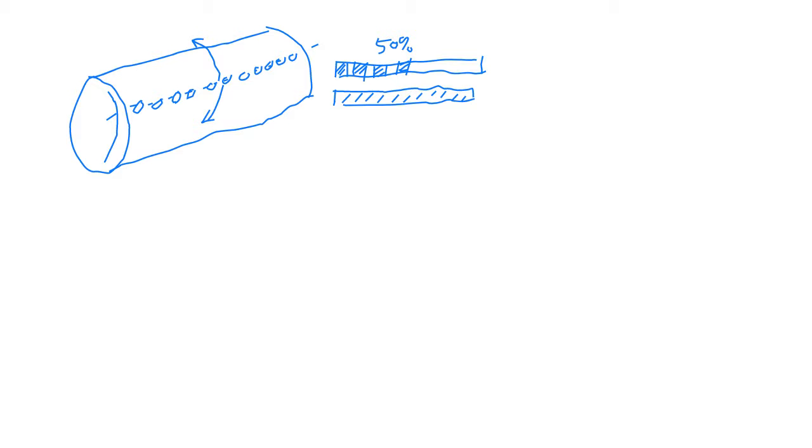Well, ASME always tells us to use the weakest part. So let's say that this is the longitudinal joint. The longitudinal joint is 100% efficient. It's welded. We've done volumetric testing in the form of X-ray, or maybe we've done volumetric testing in the form of ultrasonic testing. Okay, it's 100% examined, and so we say that joint is 100%. We go, wow, what an awesome weld. Perfect. But now we got all these holes over here.